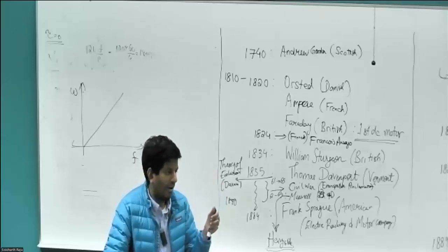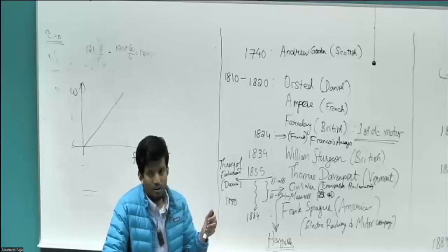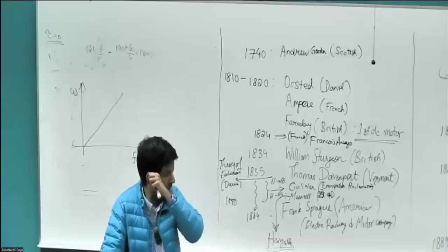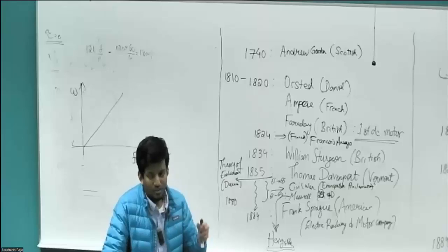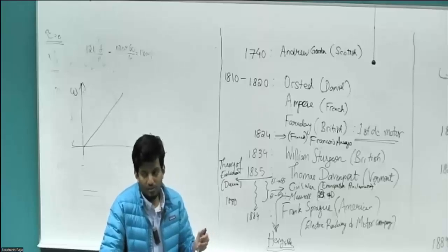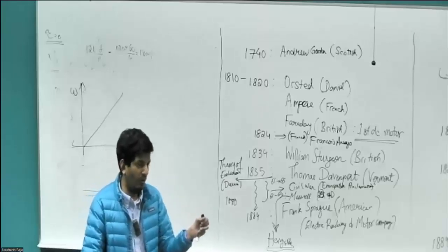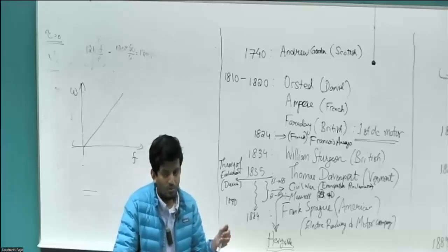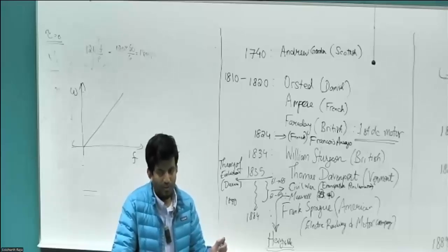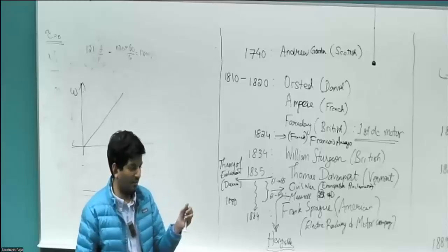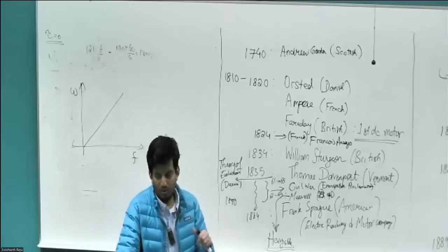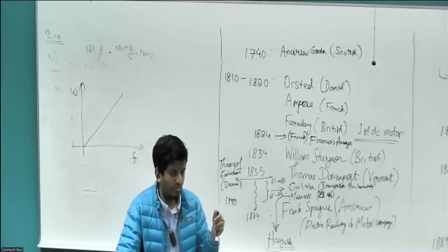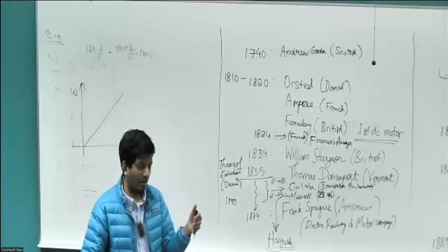For a large motor, let's say about 5 to 10 horsepower, stator resistance of about 10 milliohms is not unreasonably low. So if you connect it to 220 volts with a 10 milliohm resistor, you can think of how much current is going to flow in the winding. It is going to be far higher, orders of magnitude higher than what the motor is rated for. So there will be two things. First, it will burn the stator winding.